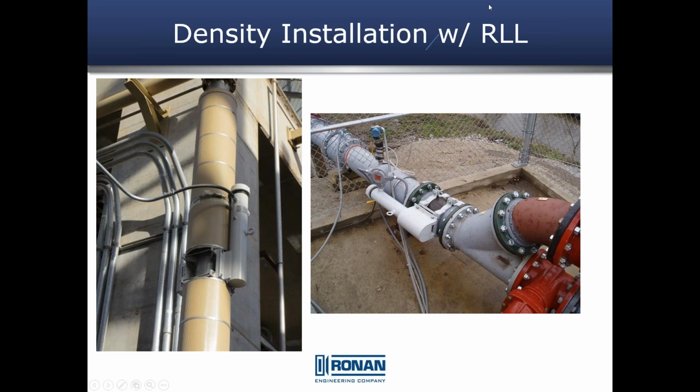See, here are a couple pictures with that low-level source. As you can see here, we're not clamping onto the insulation because it's not as rigid as a pipe. And over here is an oil pipeline coming in. And this is where they're wanting to measure API. They're also combining it with a flow meter that's down here to then give mass flow measurement.